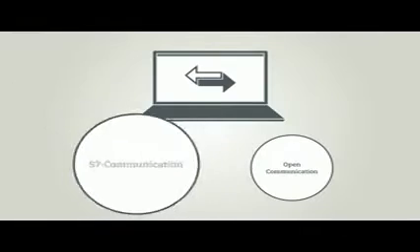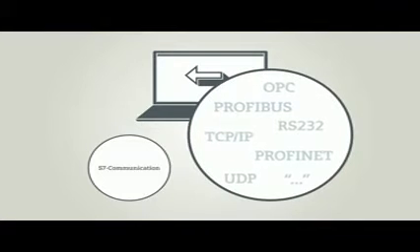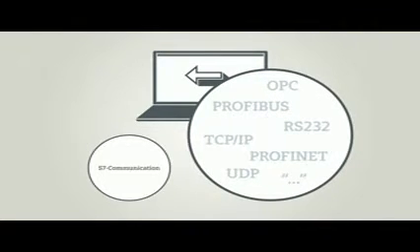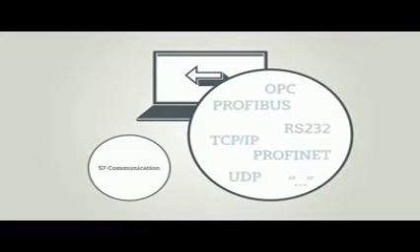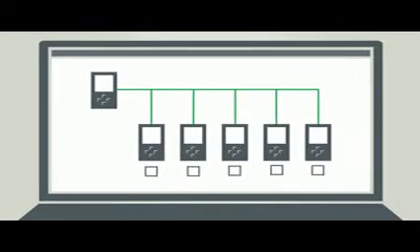The TIA portal also supports all open communication mechanisms, which are common textbook knowledge in the field of classical network technology. The easiest way to set up data communication between two controllers without programming is to use the Profinet function iDevice in the TIA portal.